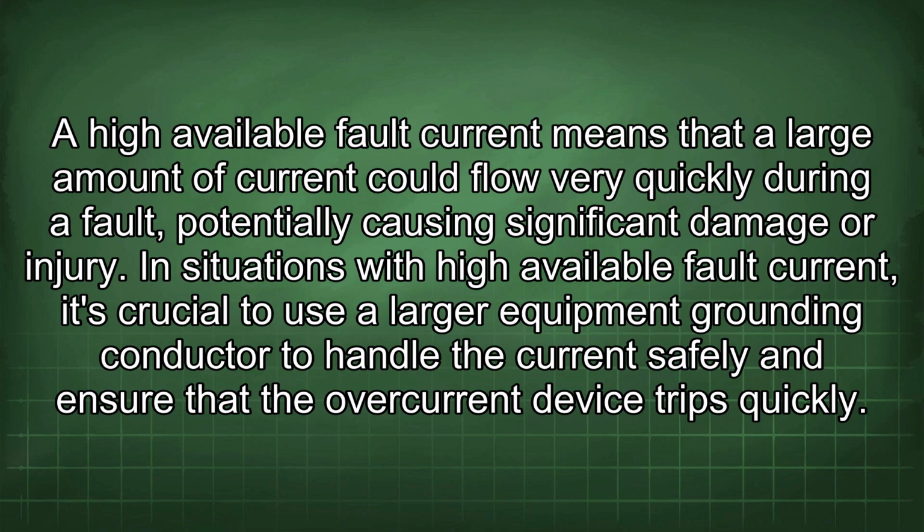In situations with high available fault current, it's crucial to use a larger equipment grounding conductor to handle the current safely and ensure that the overcurrent device trips quickly.